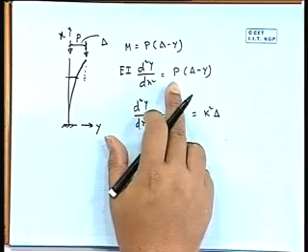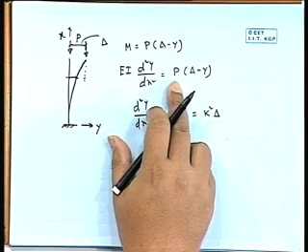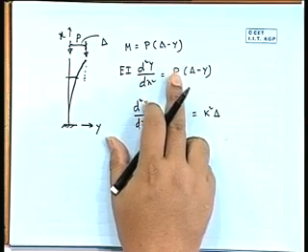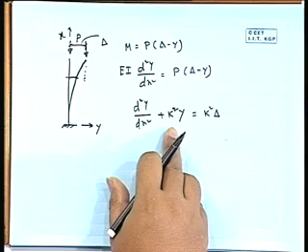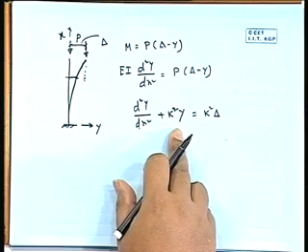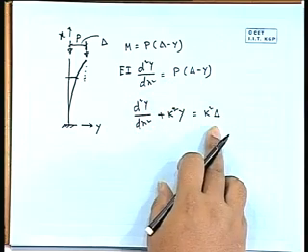The EI part you just put on the right side below P, so P by EI will be k square. So k square y, minus that part, if you take this side it will be plus k square y, and here k square delta will be on the right side.